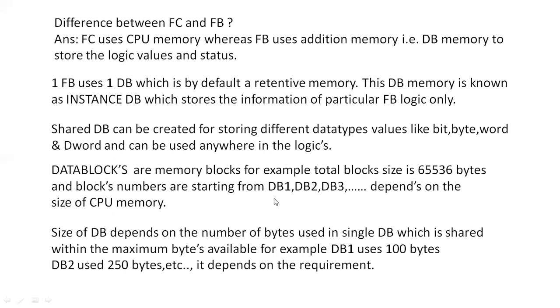Suppose I'm using one single byte for each DB, in such case how many DBs can I create? A total of 65536 DBs. That's the maximum you can create, but that's not really possible, right? Because in DB1 if I'm using 100 bytes, then minus 100. If I'm using another 250 bytes in DB2, then minus 250 again. So like that, we are sharing this total number of bytes between DB1, 2, 3, and so on. That depends on your logic and the size required in your structure.